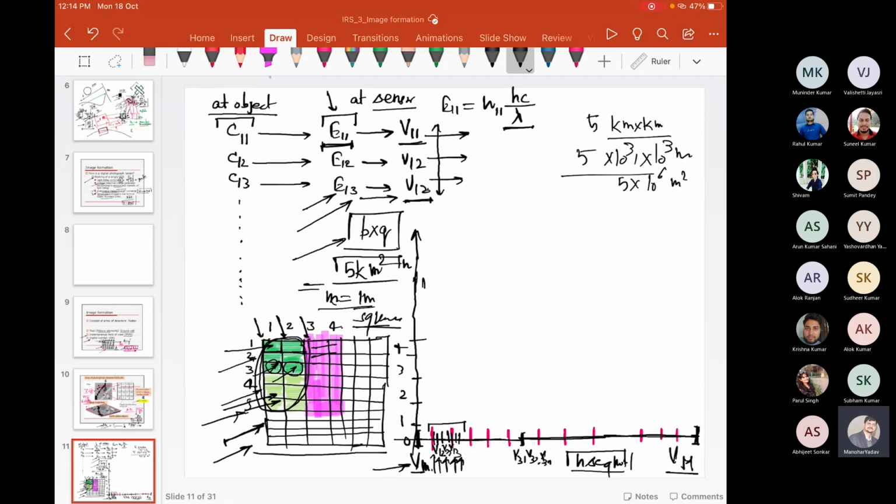How many unique digital numbers we generate depends on how many segments we divide the minimum to maximum voltage into. If we divide them into n equal segments, then we have n digital numbers available to label the particular cell. This process is called analog to digital conversion, and this is the transfer function. The transfer function which we use